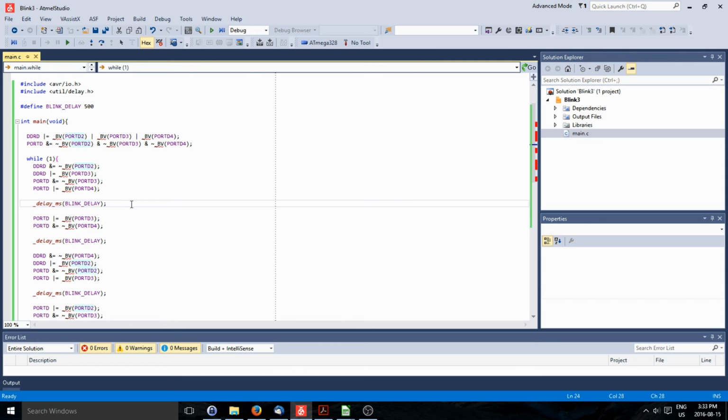They all work kind of the same way, but they're a little bit different, and I plan to go through each one of them in detail, so you understand how they work. But I'm going to use timer 0 to create the delay without wasting time. The timer does the timing. The processor can go off and do other functions, and then it gets interrupted by the timer when it times out after, say, 10 milliseconds.